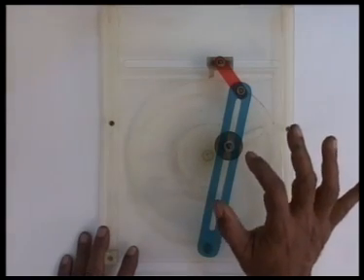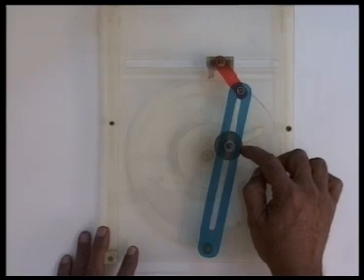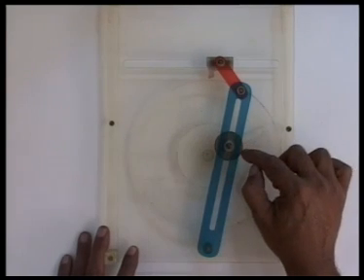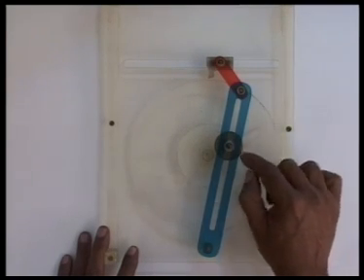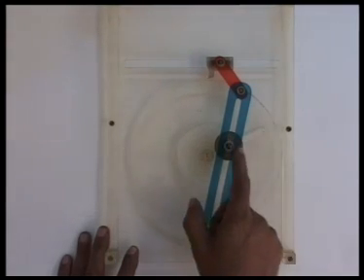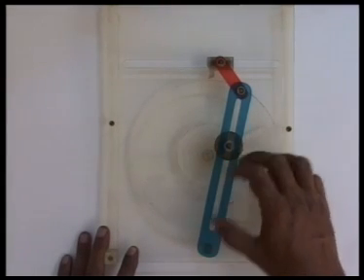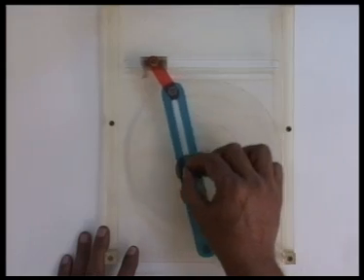Now, so that is the concept of coincident points. A2 and A3 always remain coincident because this is the block center where body 3 is hinged to body 2. A4 is a coincident point belonging to body 4, which is going in a circle with this point as center and this as radius, whereas A2 and A3 are going on a different circle.